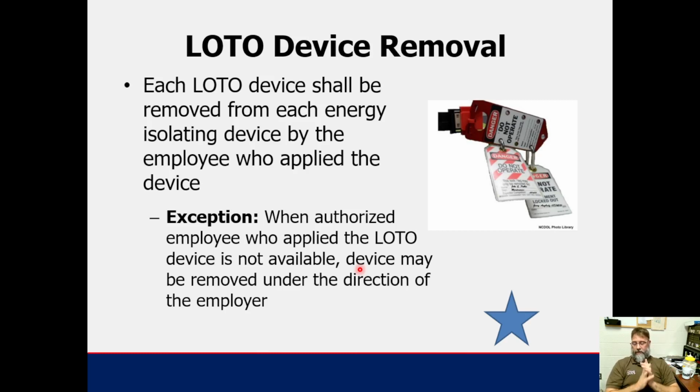You need to figure out why that lockout tagout is on there. I've actually even told my supervisor, when they say, hey, you can go remove that tag, I say, I'm not removing that tag. You are, because you're the one that's telling me it's okay.